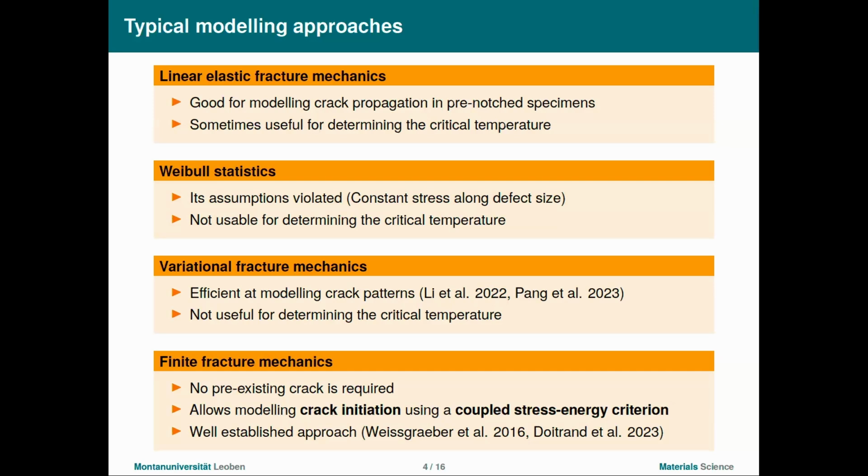The classical approach would be Weibull statistics, but it has some assumptions which we violate in this case, and not in this case only, but also in the indentation. You violate this condition of constant stress along this defect size.